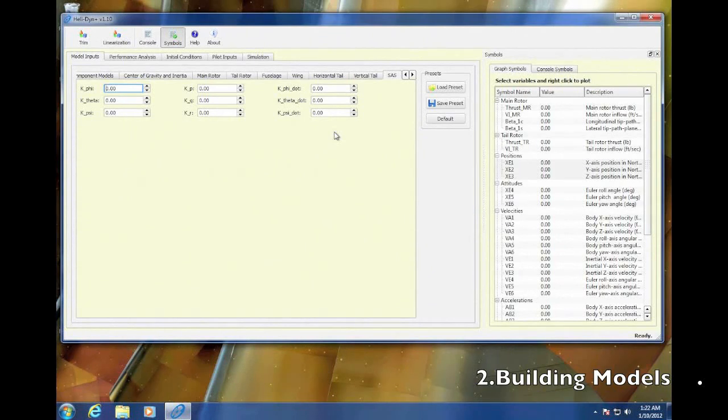A lot of helicopters use simple feedback, especially PQR feedbacks, to increase damping in some of the channels. And we found this pretty handy to adjust some of these damping values, both to include a stability augmentation system, but also from a modeling point of view. Sometimes some of the models might not model enough of the damping, for instance, and this is where you can make little adjustments.